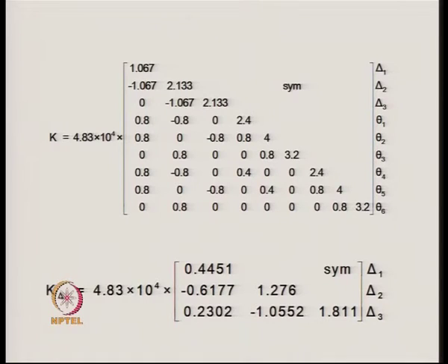Then we assemble the elemental stiffness matrices to find the total stiffness matrix and go ahead with the calculation. When the system is a weak beam strong column, then for both 2D and 3D frames, the problem becomes the same, because the beams can undergo only one-way bending. Therefore, the problem becomes easier, but the only thing to be taken into account is that whenever a hinge forms at the beam cross section, the rotations are to be condensed out.